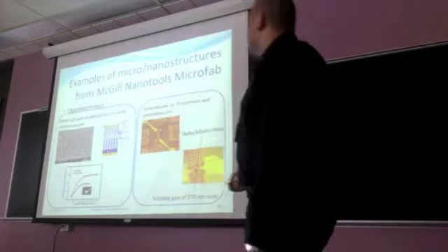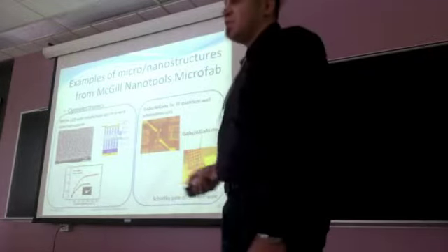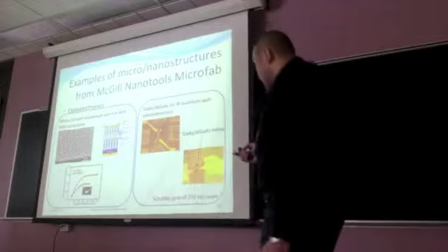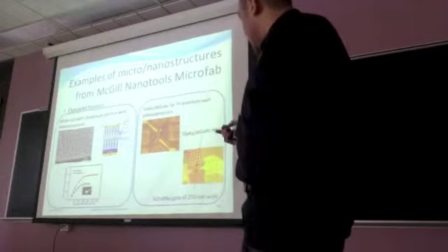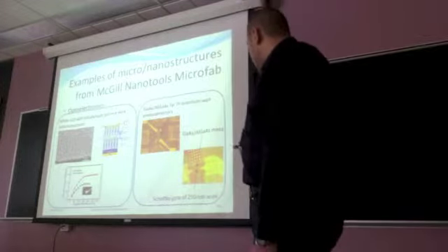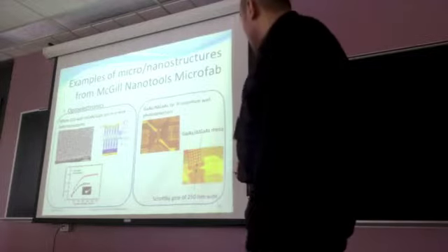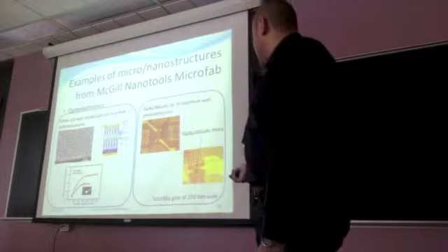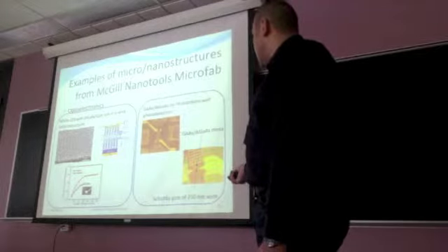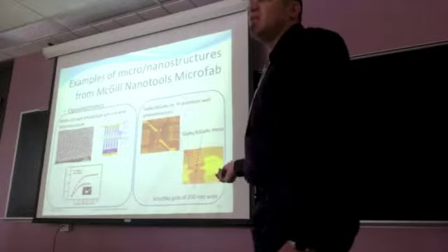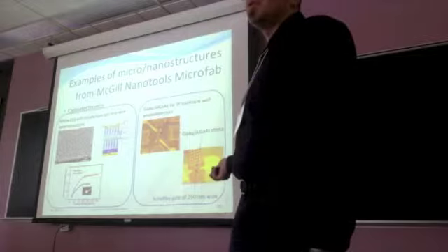Gallium arsenide and aluminium gallium arsenide quantum well photodetectors were fabricated in the fab. The active area for detection was made by reactive ion etching of this material, and the Schottky gates on these detectors were made by e-beam lithography and electron beam evaporation of metal.